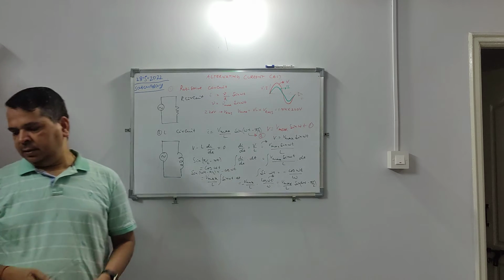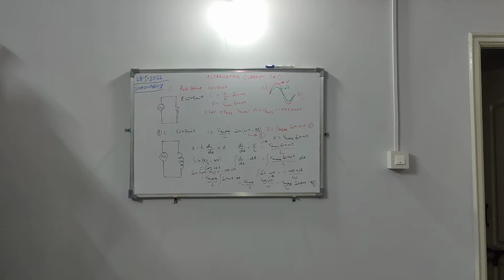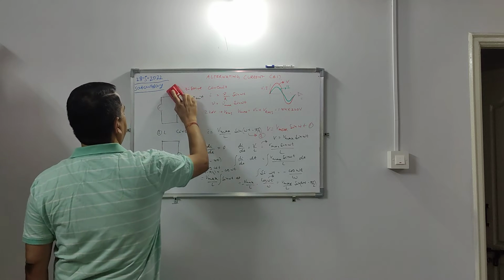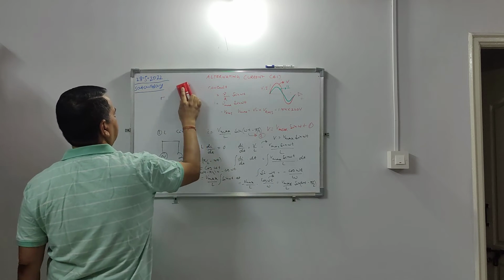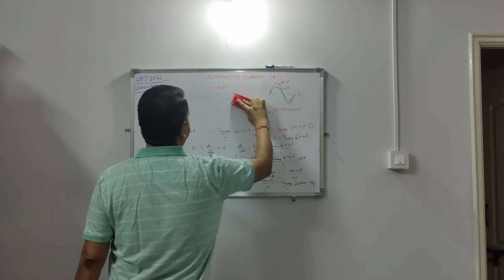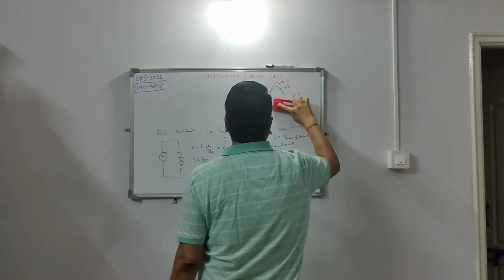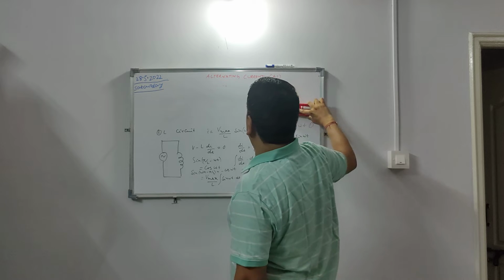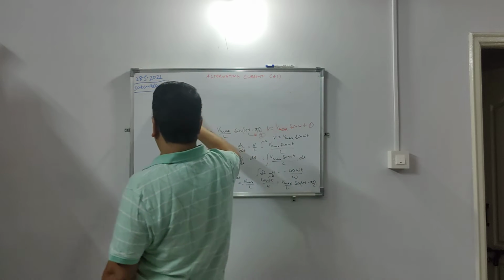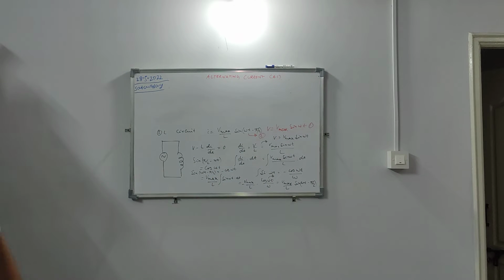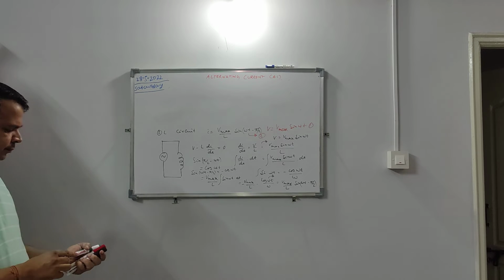So a capacitive circuit or an inductive circuit is called wattless power because cos 90 is equal to 0. Okay, so let me draw this resistive part, and we will draw the diagram of time versus voltage and current. So for the inductive circuit, how does it look?